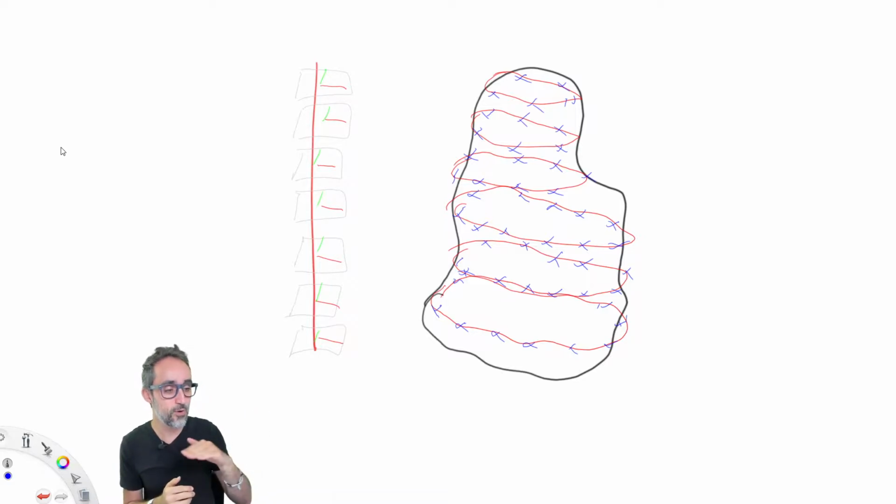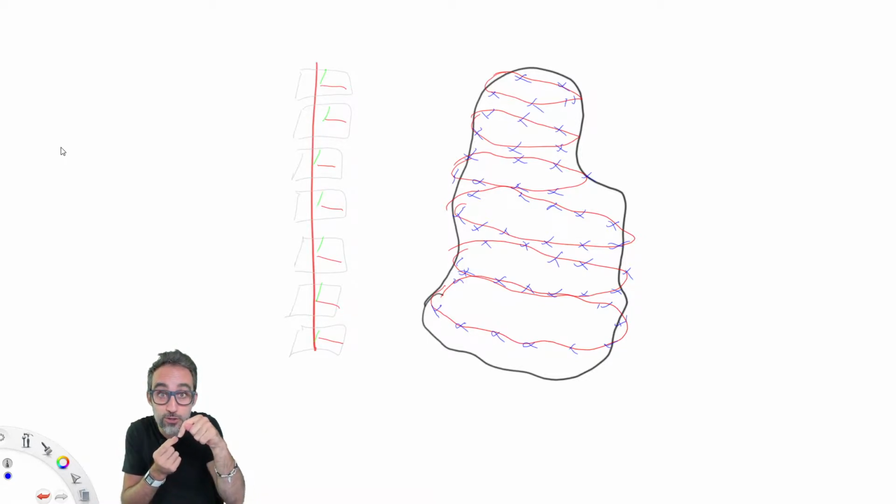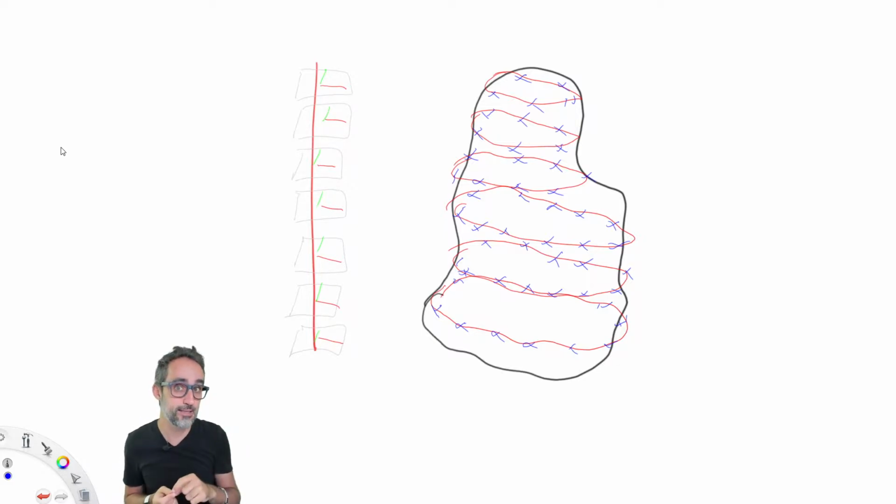But also discretizing a contour that is made out of polygons, because when you cut a triangle you get straight line segments, is a very simple thing to do, and is very convenient for a 3D printer in particular, because a 3D printer can only do straight line segments. It cannot move in a perfectly smooth curve. So when we want to do curves with a 3D print, we do tons and tons of tiny straight line segments. So that's why meshes are the de facto standard for 3D printing.